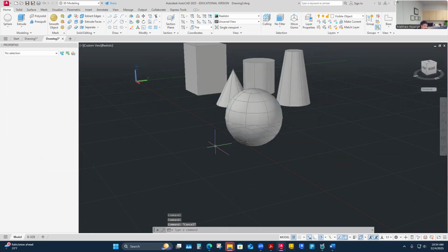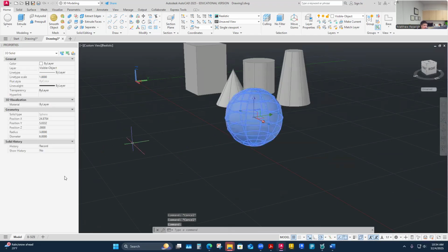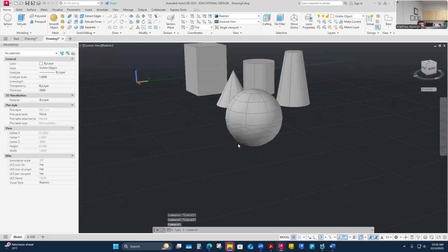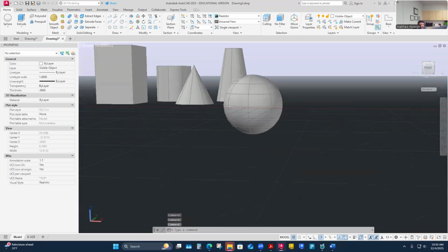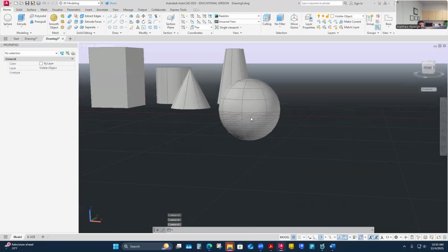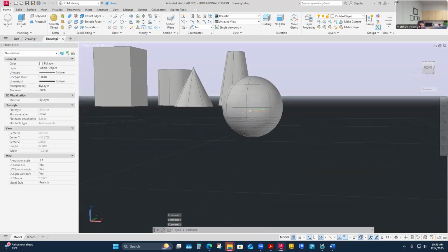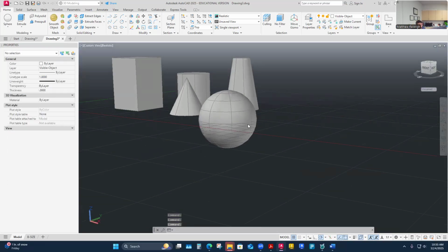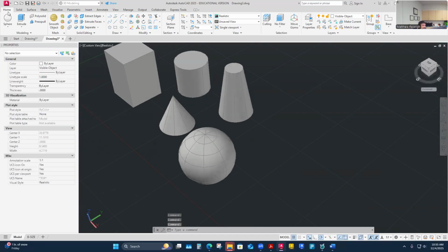It's the same way if you select this geometry and you have your properties panel up, you get some control over it from your properties panel. Here's the diameters and radiuses. I think it's the same way with my cone. It'll show what its height is, what its base radius is. So you can change those parameters from your properties panel. Okay, so there's a sphere because I was on the top grid pattern. It's going to show that's the center point, and it's going to be kind of below that a little bit and above it.